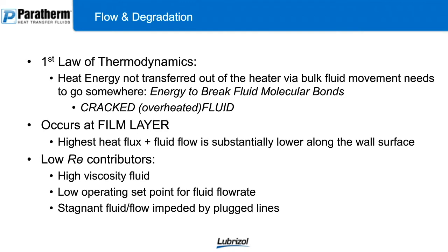So if you don't have proper flow dynamics and turbulent flow, not removing that heat and moving it elsewhere, it's actually going to be concentrated in breaking down your fluid. This is going to result in cracked or overheated fluid. This creates a serious issue in any system because when you crack your fluid, not only do you decrease the efficiency of it and create unsafe areas, you actually will foul the fluid into the system, creating even more issues, maintenance issues down the road, decreased flow dynamics, and just a compounded problem.